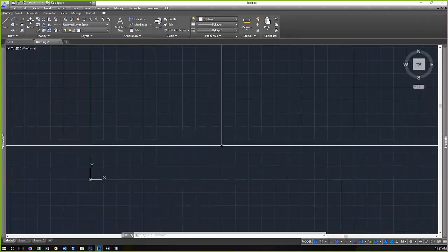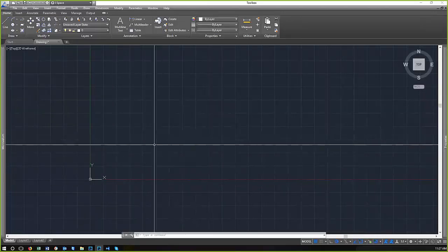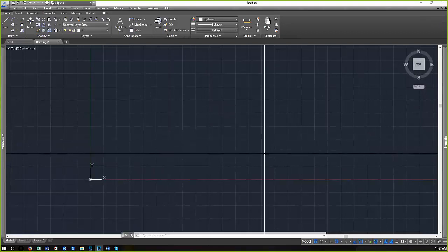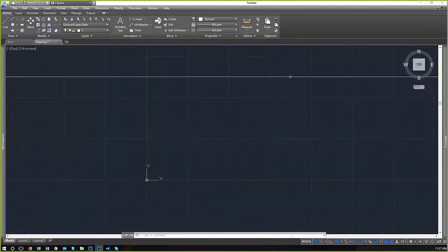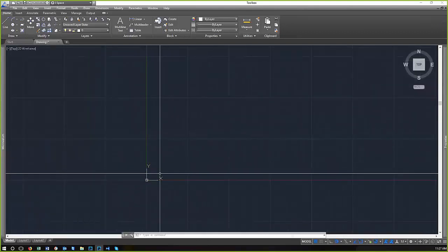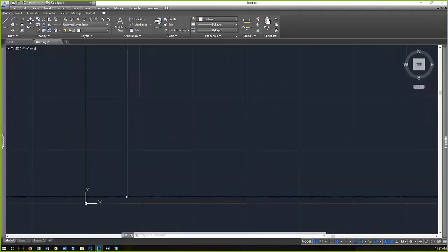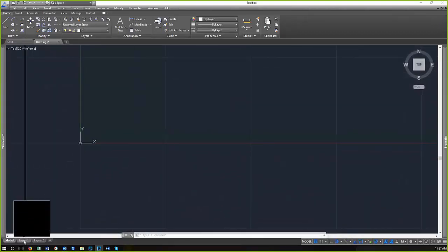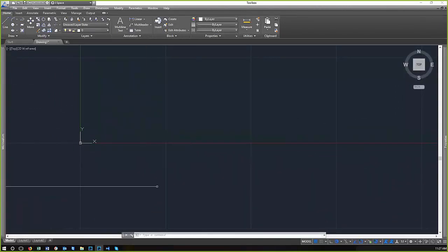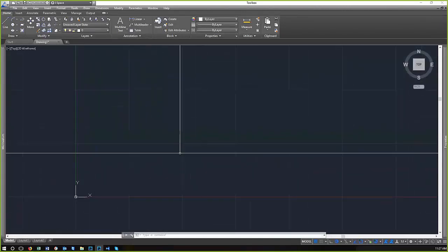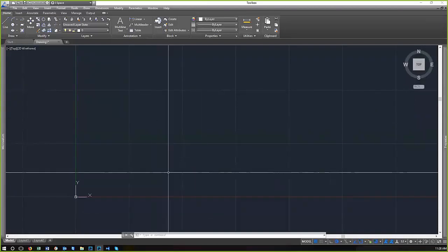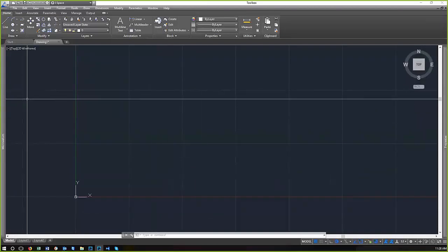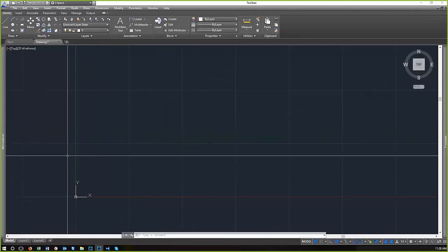So then you'd have a drawing of cabinetry, in our case, and then you'd have a section, and that section would be much larger than the drawing of the cabinetry. But that's not necessary now since the implementation of Paperspace. So we want to recommend drawing everything in model space to a full scale, and then later going in and being able to scale those using Paperspace.